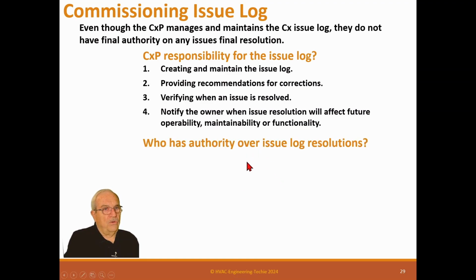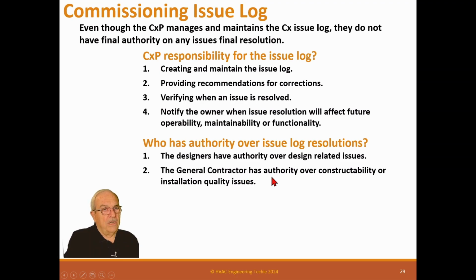Who has authority over issue resolution? The designers have authority over design-related issues. That's what they're paying them for, so they have responsibility for that. The general contractor has authority over constructability or installation quality issues.